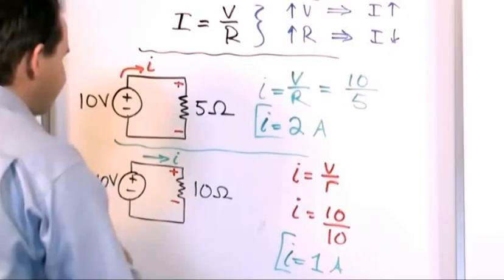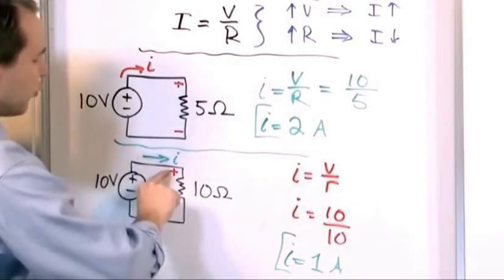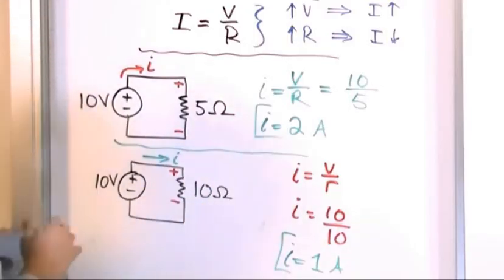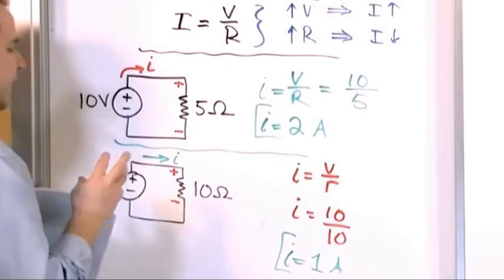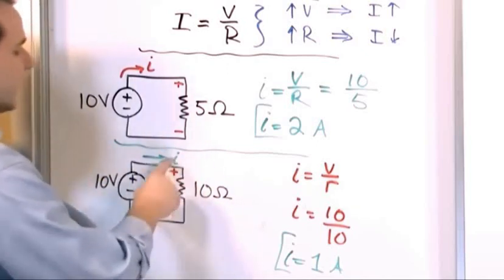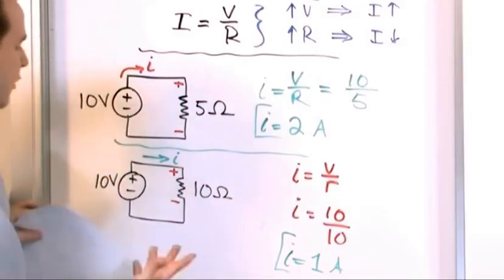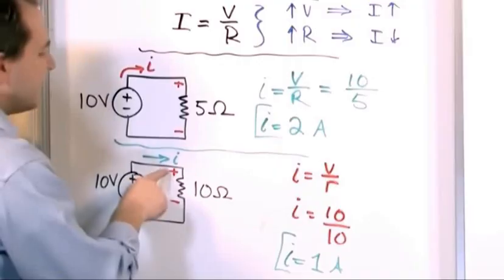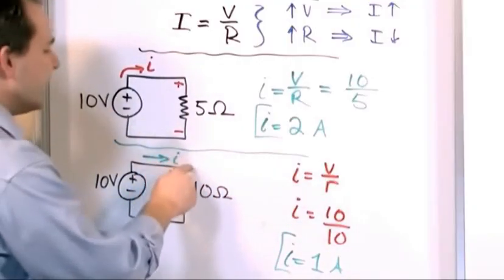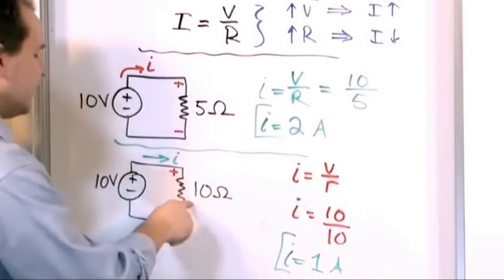You need to think of it as almost like the voltage that's across the resistor is what pushes the current through this resistance, for lack of a better word. And the way we do the sign convention in engineering is that whenever you're talking about a passive component like a resistor, a capacitor or inductor, then the voltage drop goes in the direction, positive to negative, of the current flow.